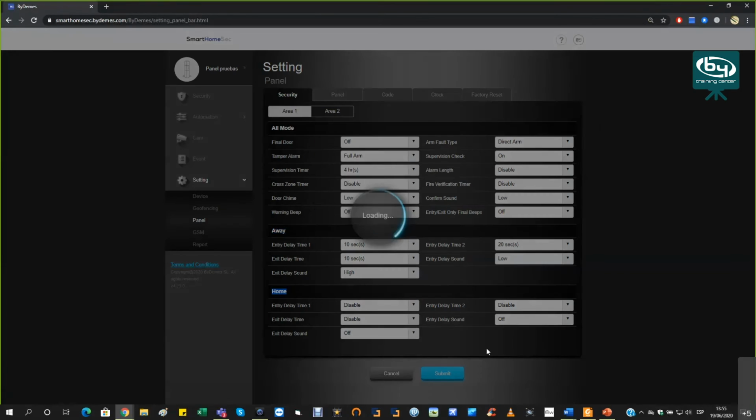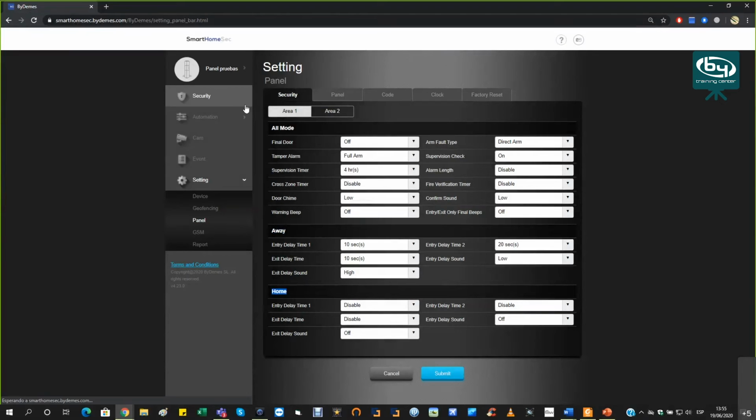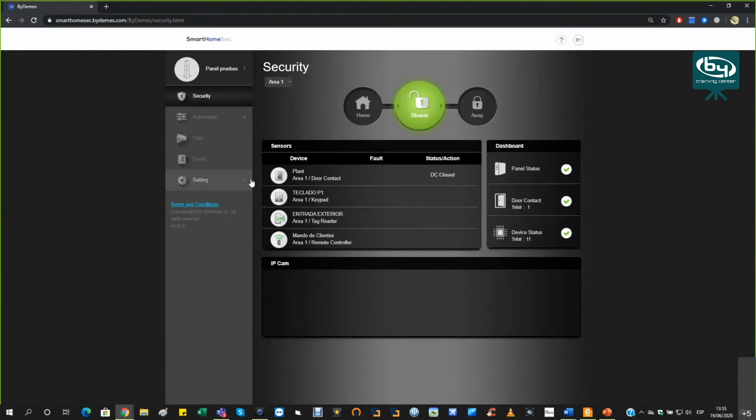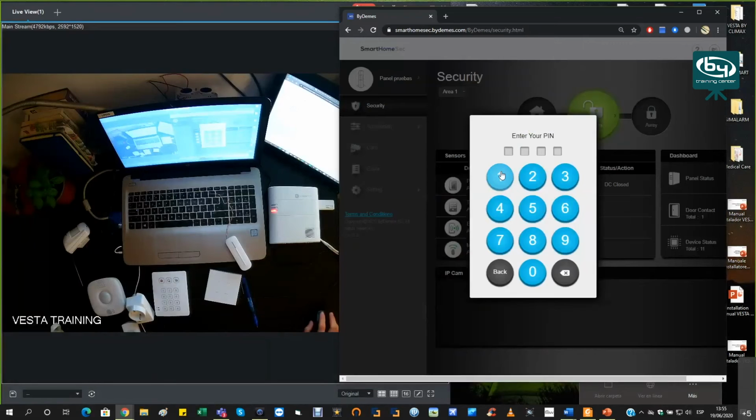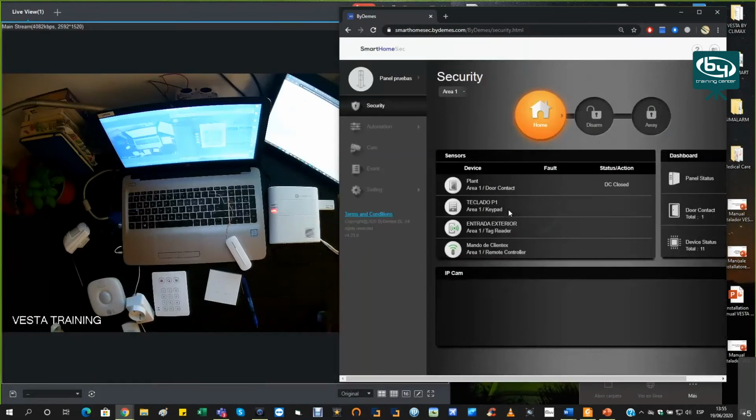Yeah. Thank you. No problem. I will show you. In this case, I have home arm exit delay disabled. So in this case, when I click on home arm, you will not hear anything, and I don't have a time. I will show you. 1, 2, 3, and 4. Okay. The system is armed, and you didn't hear the panel, and this is all.